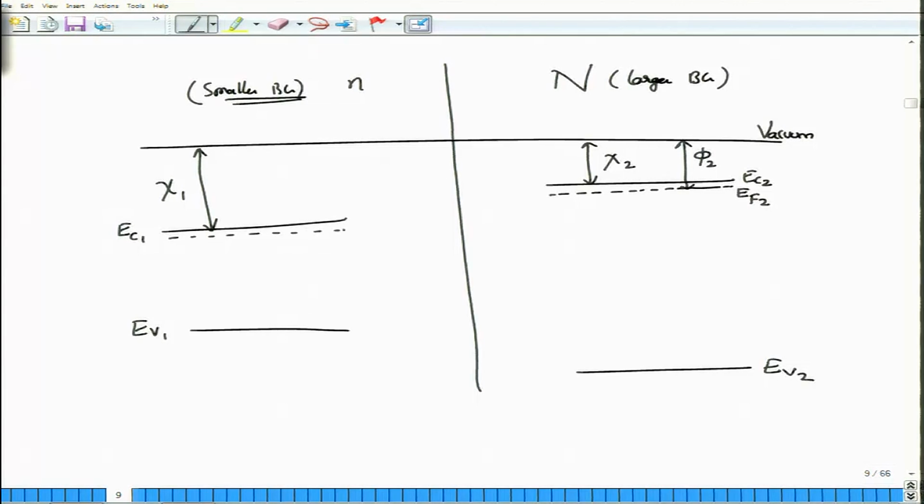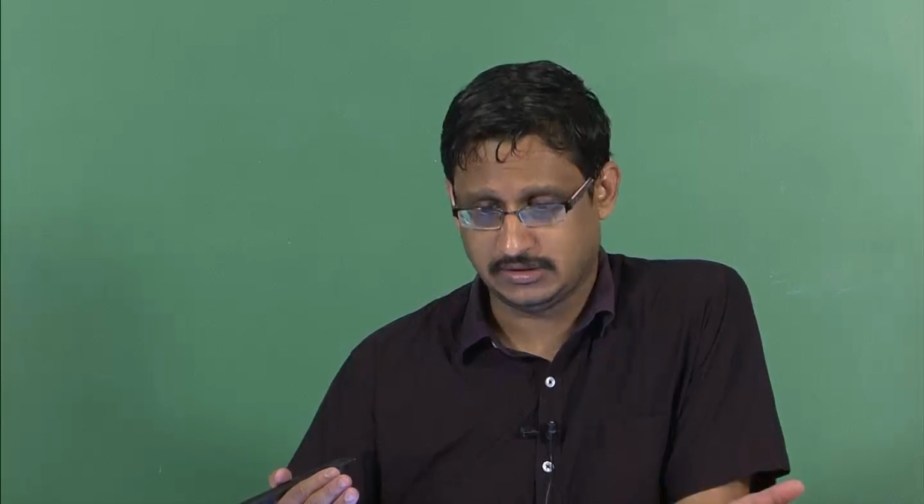As before, the Fermi level has to be found near the conduction band, therefore, this is located close to the conduction band as it is. So, this is a junction far away from whatever is happening. But at the junction itself, sometimes also called the metallurgical junction, what really happens? This is an n-type material, capital N, but it is still nevertheless an n-type material. Therefore, even when you merge these two materials together, the overall characteristic should still be an n-type material characteristic. That is very crucial. When you merge a small n and a capital N, the overall characteristic should still be an n-type material.